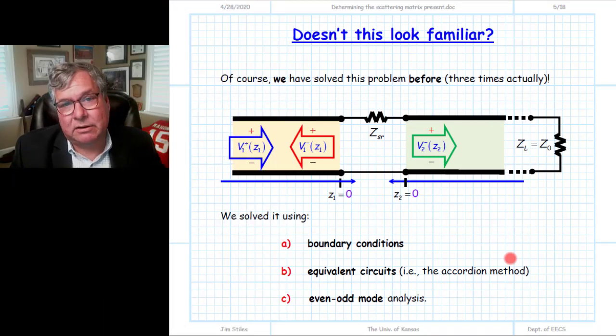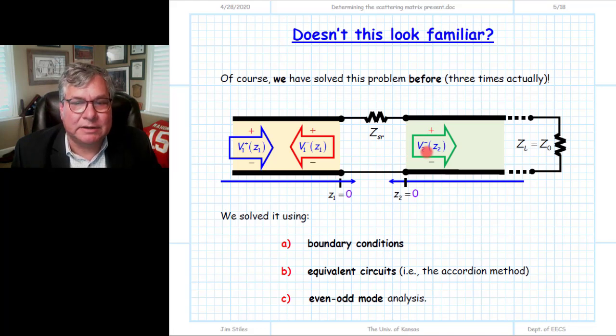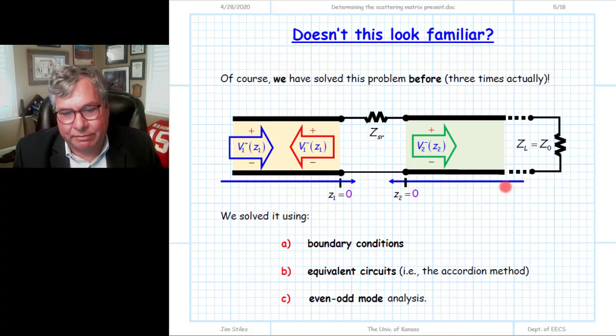So this is what our problem would look like. We take our 2-port device and we terminate the second transmission line in a matched load, a resistor numerically equal to Z0. And of course that ensures then that the incident wave onto port 2 is equal to 0. The total voltage along this transmission line here consists only of its minus wave voltage, minus wave because it's propagating away from the port. It is the scattered wave.